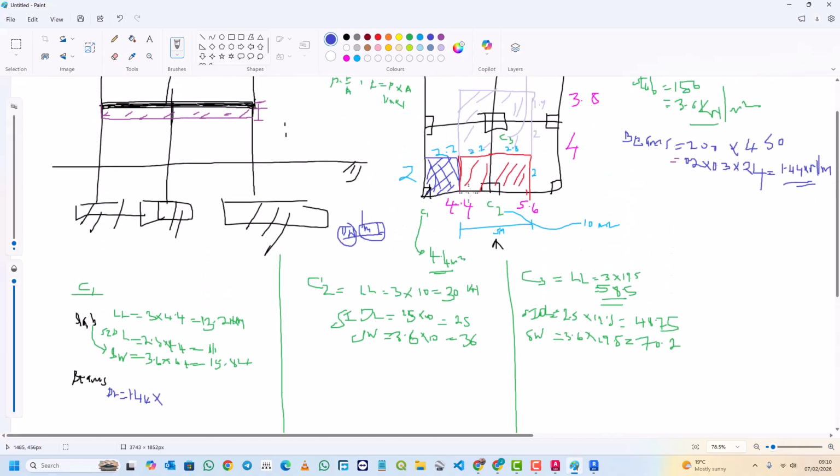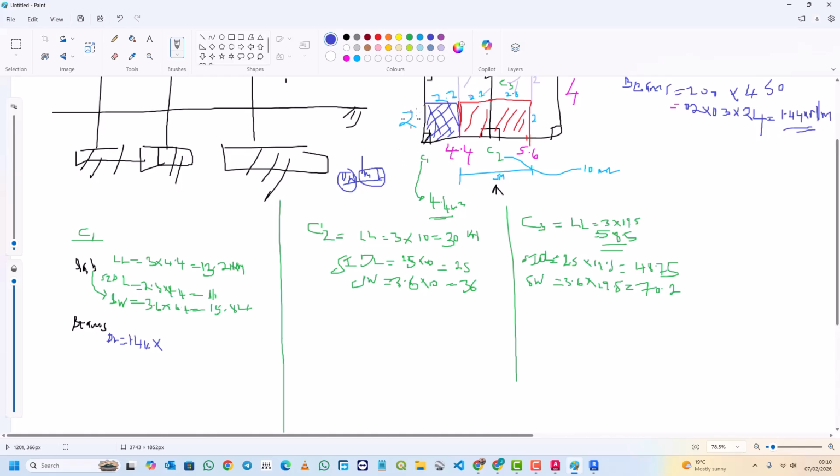And the length of the beam in this case is this length 2 and this length 2.2, the total length that this beam is supporting. So when you add this 2 plus 2.2, you must get 4.2. So I'll just multiply by 4.2 as the length here. So when you do this, it will be very simple. You just multiply by 4.2, and here I'll get 6.048.